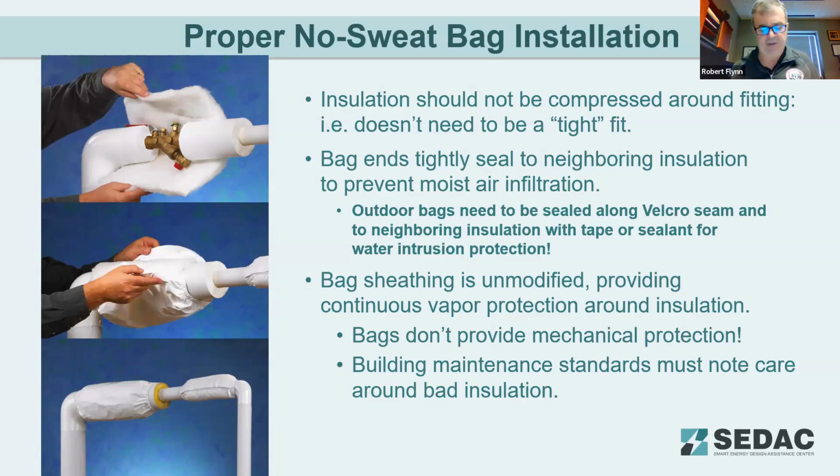I think, Sean, there might be a question from one of the people in the audience regarding valves. Does the code require insulation at valves and strainers? If it's Sean, maybe you want to take that specifically. That question. For any fitting on pipe sizes greater than 1 inch in diameter. So if it's for 1 inch or smaller piping, the code does not require that strainers, fittings, and things have insulation on them. But for larger components of the piping system above that 1 inch threshold, yes, the code does require insulation at those fittings and joints, valves.